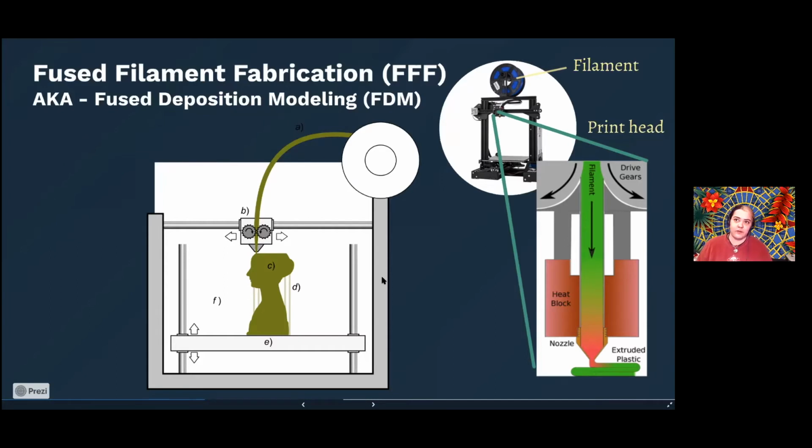There's several different types of printers. There's Cartesian, which is the one where the bed doesn't raise, and then there's the XYZs where it does. They both work similarly though. So the nozzle goes up, it prints a pattern, it goes up, it prints a pattern, just over and over until you have your model there on your bed to pull and have. So yeah, as you can see in this diagram, that's how the filament goes through. It gets heated and it turns into liquid right about here, and then comes out and immediately cools.